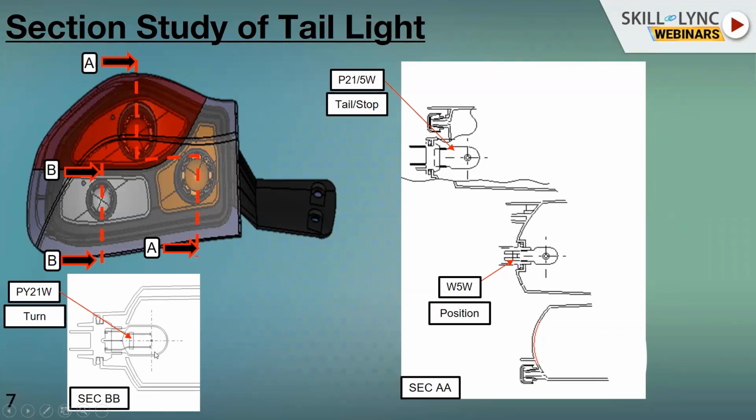So this is being used for the turn indication requirement. For the housing, we are using PP material, and if we are going with glue or vibration welding, then ABS material is also used for the housing. And as we discussed earlier, for the lens we are using PMMA material, and this is the standard bulb.